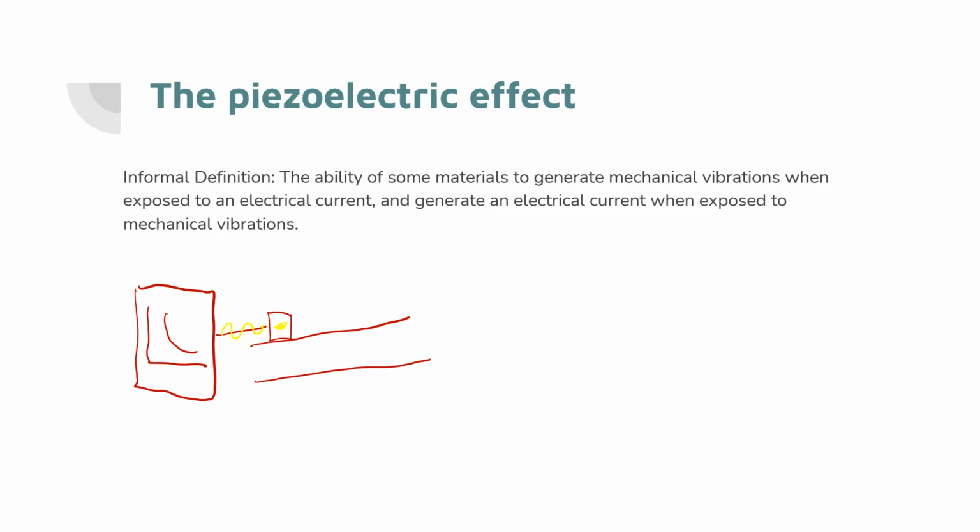The crystal then generates sound that travels down into the material. The sound will hit the back of the material and be reflected back. This will then be caught by the crystal, which changes this mechanical vibration back into electrical. The electrical is sent back to the ultrasonic set, and on our screen we will see a response.